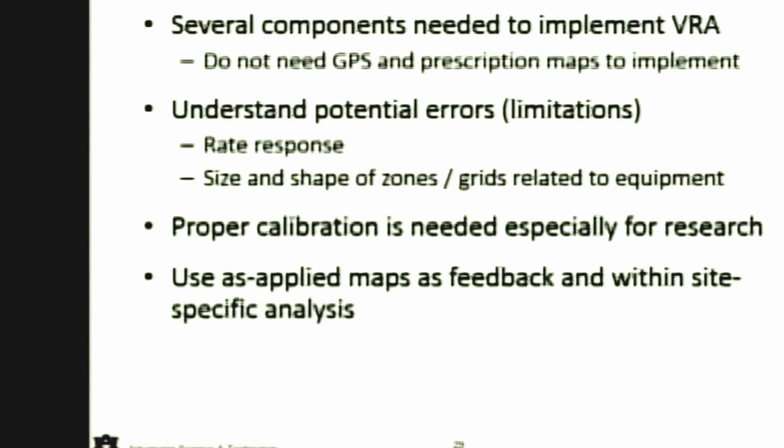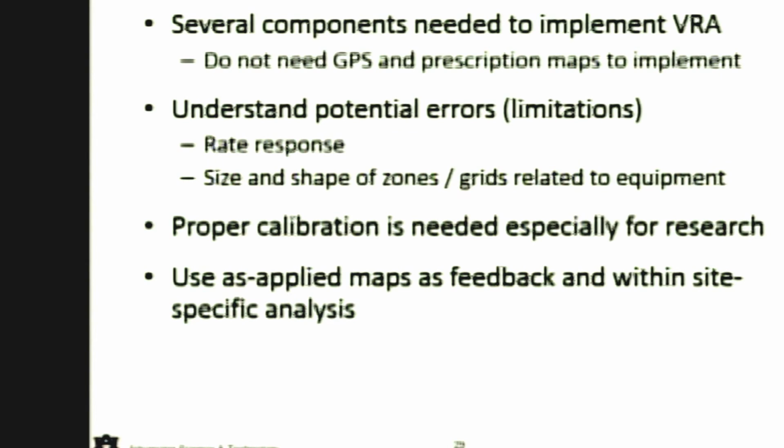We'll do that in another lesson, but the idea here is the technology can really advance the fine-tuning and getting your target rates right, whether that's population on a planter or pounds per acre that you're putting out with your spreaders. We can do that much more accurately with this technology, and that's probably the biggest benefit it provides: the ability to calibrate and ensure you're within 1 or 2% of what your target is out there.